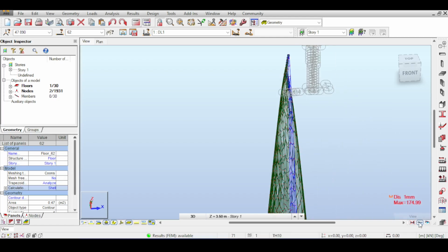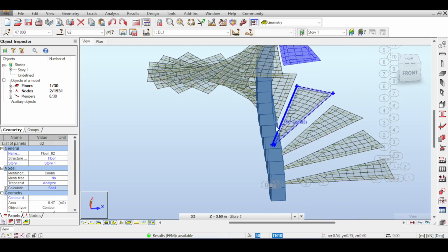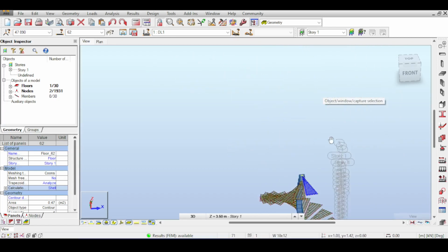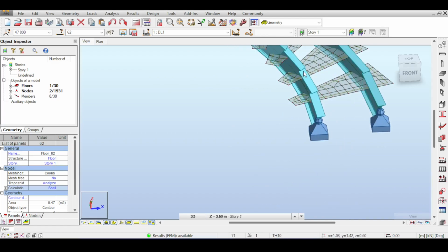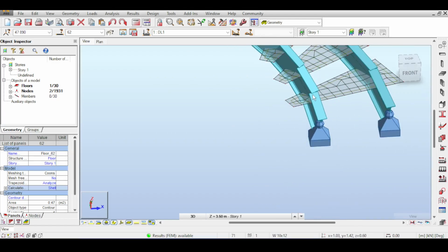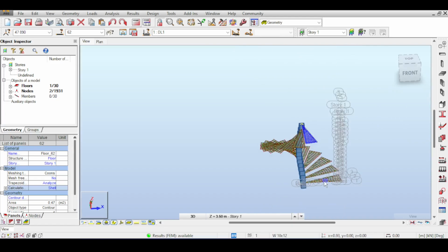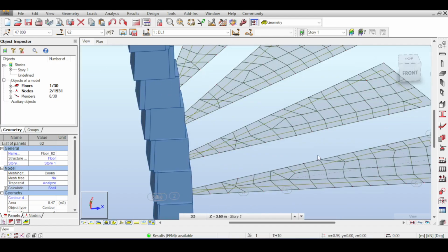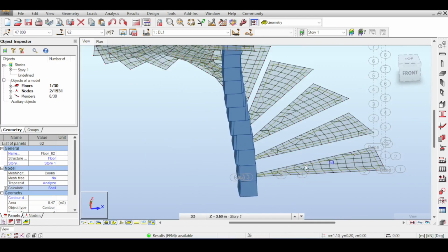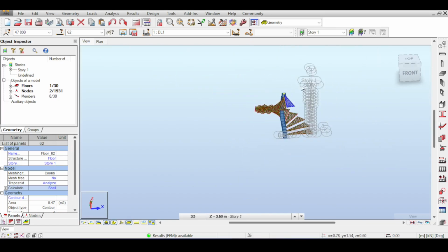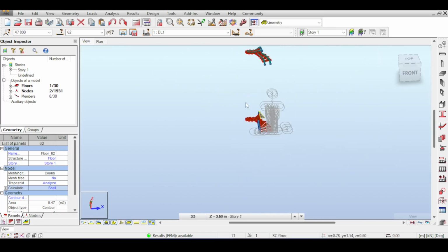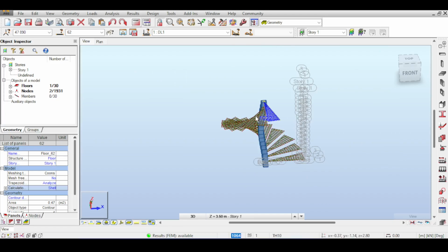Oh yeah, of course. Because it's cantilevered, my 10 millimeter thickness will not be enough. When it was supported by two beams, 10 millimeter thickness might be okay-ish, but having a cantilever, the 10 millimeter thickness will never be okay, so it must be fixed. But okay, at least mission accomplished. We have analyzed and successfully modeled this staircase.